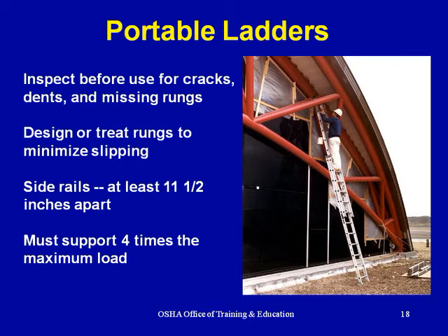Portable ladders. Inspect before use for cracks, dents, and missing rungs. Design or treat rungs to minimize slipping. Side rails, at least 11.5 inches apart. Must support 4 times the maximum load.